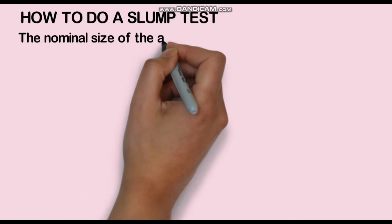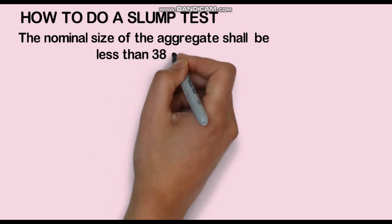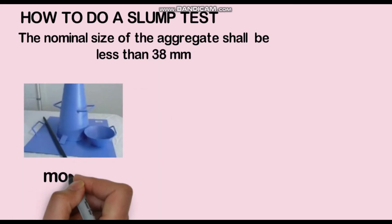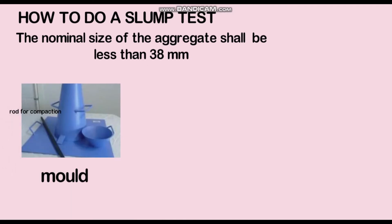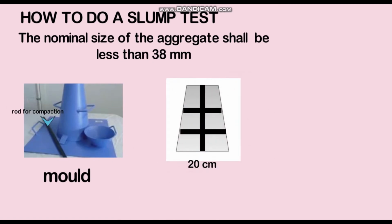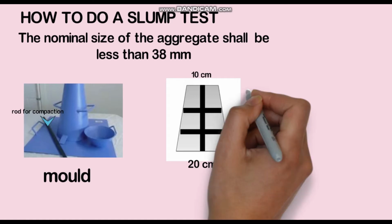The nominal size of the aggregate shall be less than 38 mm. This is the slump mold. The slump mold consists of a metal cone that is 20 cm bottom diameter and 10 cm top diameter. Total height is around 30 cm.